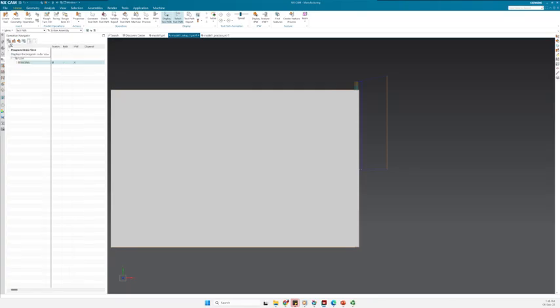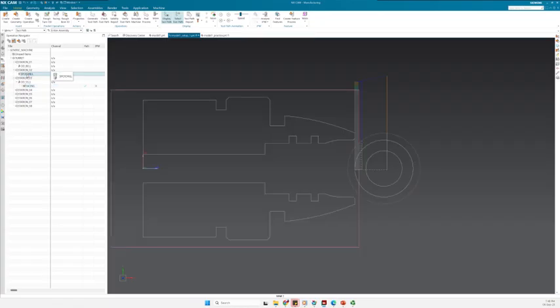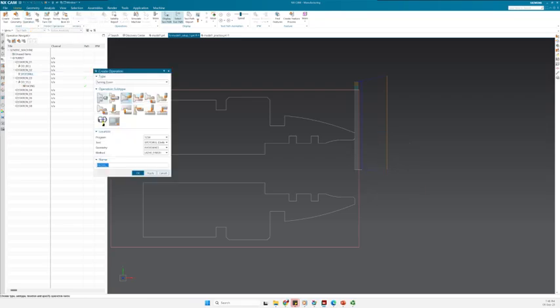As you remember, you can see that we have already the spot drill defined in this section. So then what we need to do is just to create a new operation. We go create a new operation, spot drill, center line, into the same program. Spot drill is correctly selected. Again, we are going to work on the part itself, so avoidance. And then here we're going to select the lathe center line.